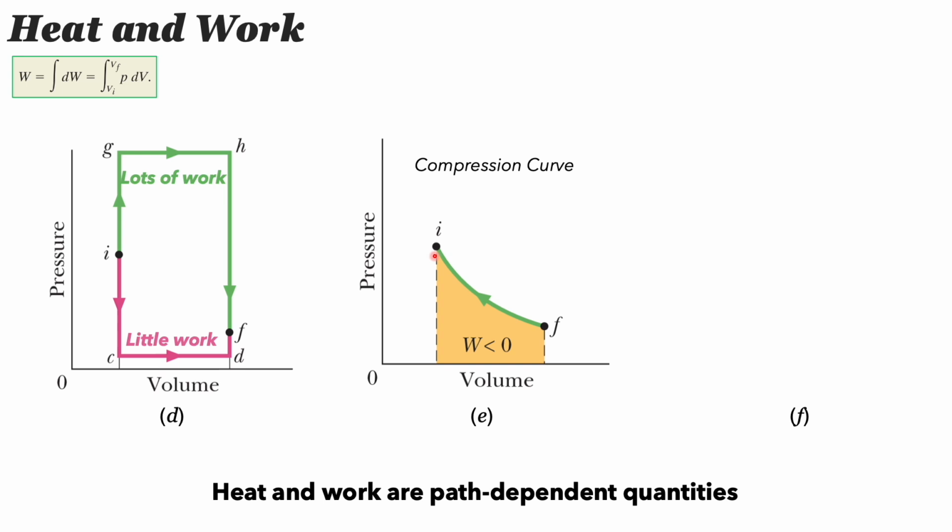So the pressure is increased, that compressed the gas, which means that the work is done on the system. Therefore the work done is considered negative, because we always consider the work done by the system. So it is done against it, therefore the work done is negative, but the value of work done will still remain the area under the curve, because the work is done on the system, that is why it is negative.